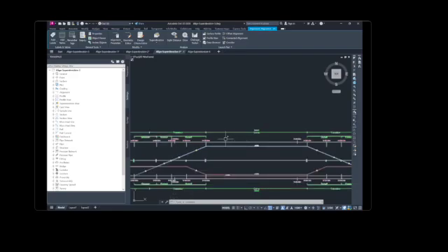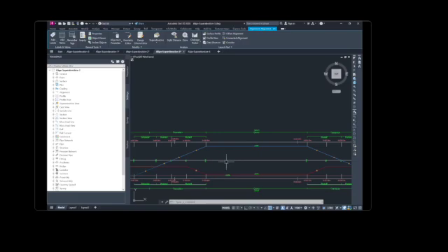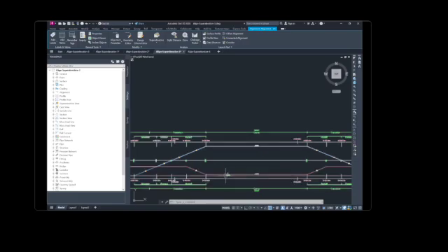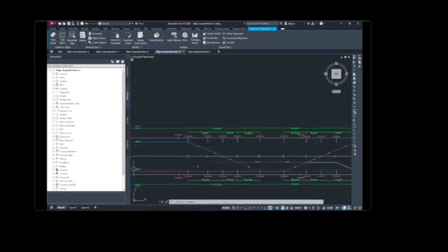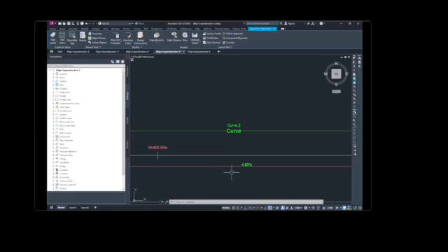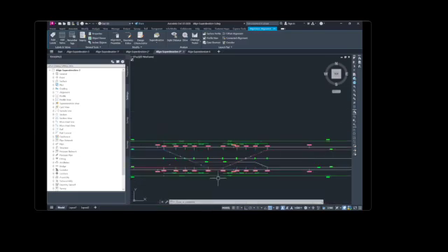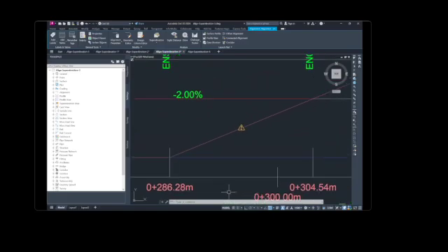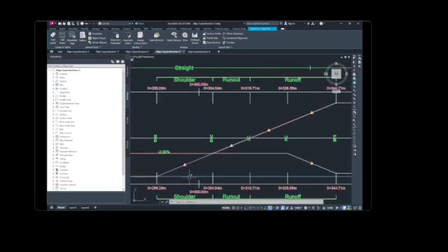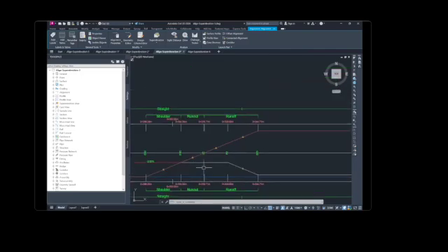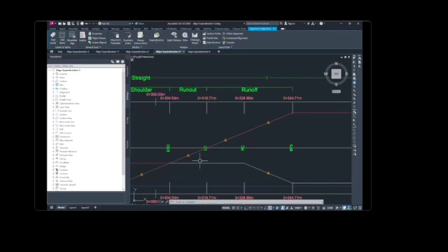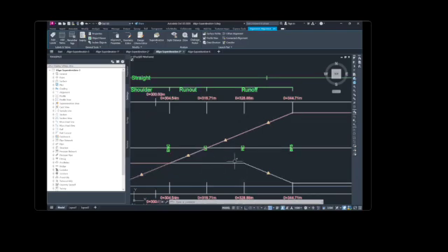The white line represents a baseline of 0% slope, and the red and blue lines represent the slopes of the outside lines and outside shoulders. So now in curve 2, at station 0 plus 286.28, the left shoulder light red starts to transition from the normal minus 5%.